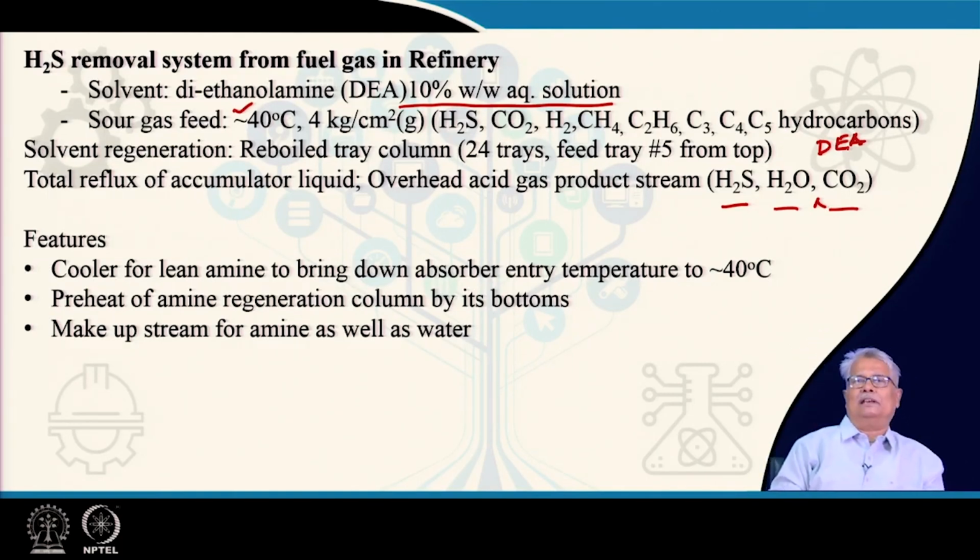You will also note that the choice of the solvent diethanolamine is for a very specific purpose. It is the weak chemical bond it forms with H2S and carbon dioxide, which increases the liquid phase solvent capacity to absorb much higher. That means the effective solubility with only water, compared to the effective solubility with a 10% diethanolamine solution, is many times higher for the DEA solution.